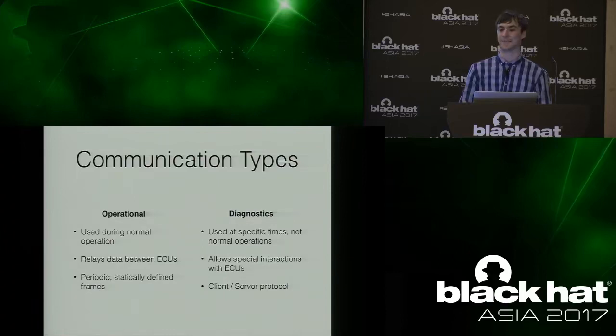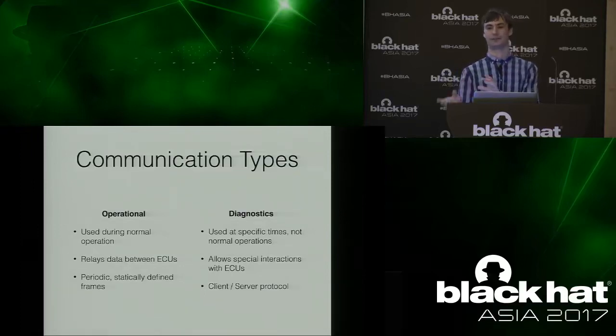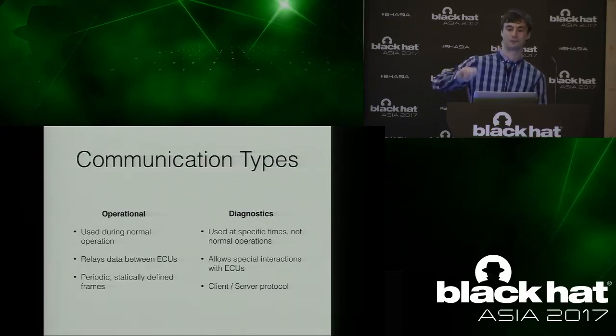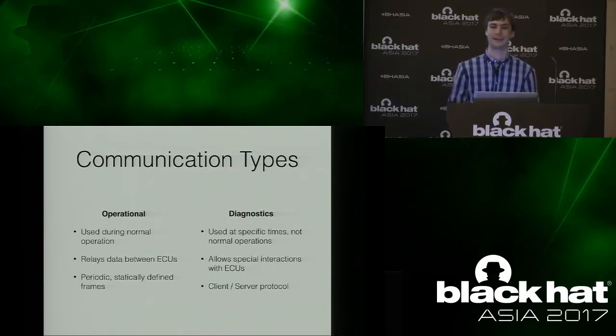And they're all statically defined, so in one message, like byte 6 will always be the same thing. One example, when you start the car, you might take the key, turn it from off to accessory, and one byte might change from 0 to 1. And then whenever you go to run from accessory, that might be 1 to 2, then switch to crank, and now it's switching from 2 to 3. And that's the scheme that at least one company uses to encode that data.